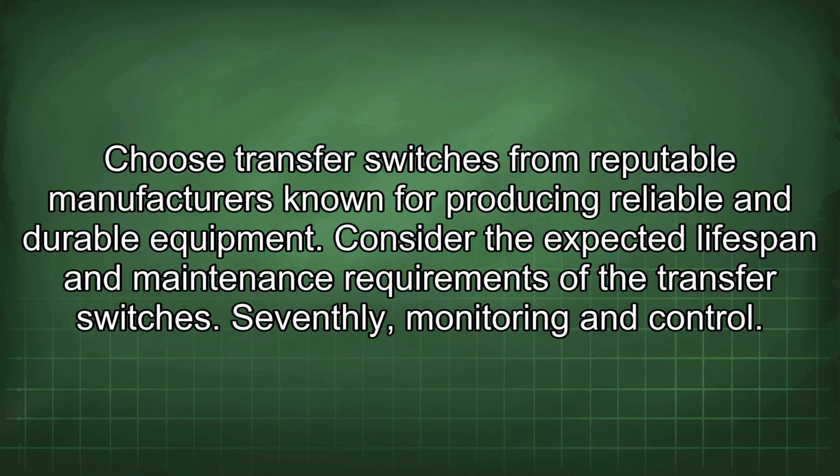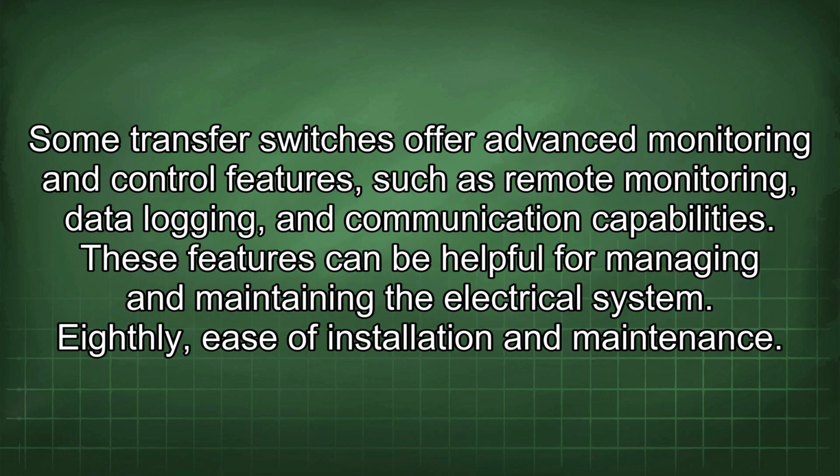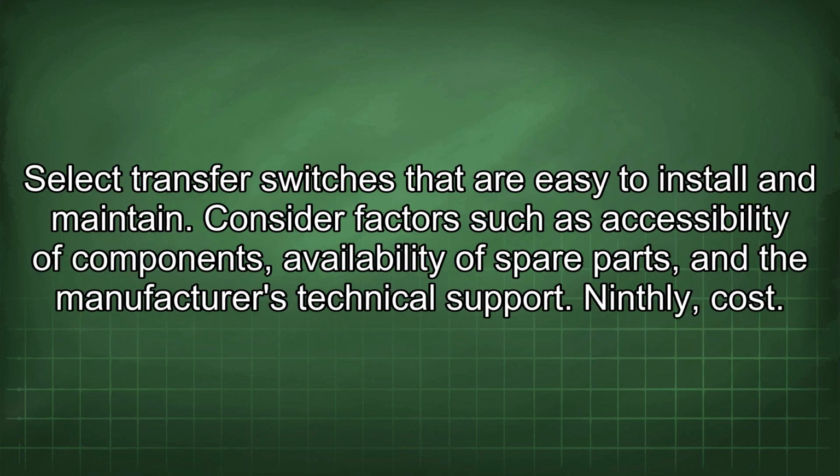Seventhly, monitoring and control. Some transfer switches offer advanced monitoring and control features, such as remote monitoring, data logging, and communication capabilities. These features can be helpful for managing and maintaining the electrical system. Eighthly, ease of installation and maintenance. Select transfer switches that are easy to install and maintain. Consider factors such as accessibility of components, availability of spare parts, and the manufacturer's technical support.